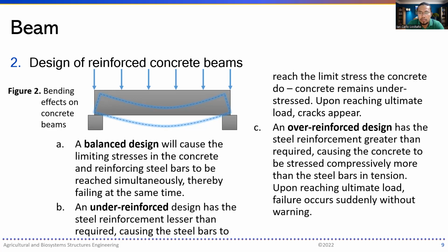and that causes dangers in construction. In most cases of accidents where buildings collapse without any sign, it's more important to focus on making a balanced design or even an under-reinforced structure, so that before the steel could reach ultimate load, the cracks already appear on the concrete, so that the engineer is able to remedy the situation.